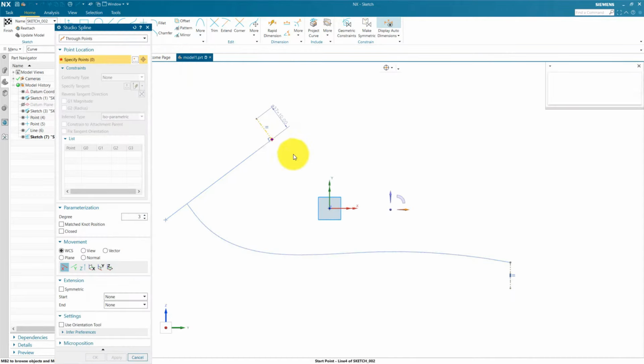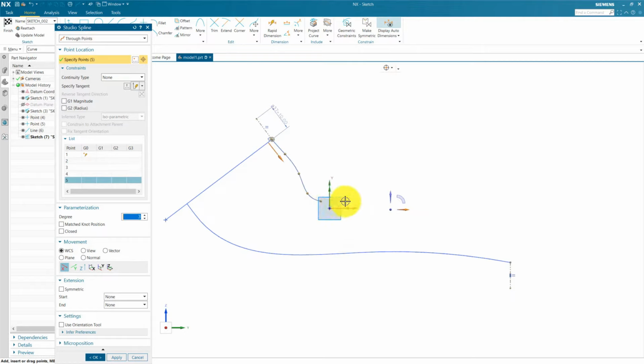Okay, point, start selecting point, and after creating rough spline, we will define dimension, and it will automatically take right shape according to dimension. You can also remove or add point later anytime. So don't worry about how many point we need to take here.